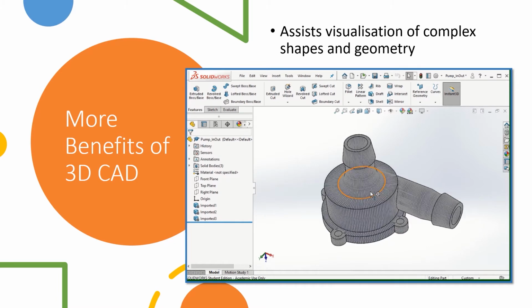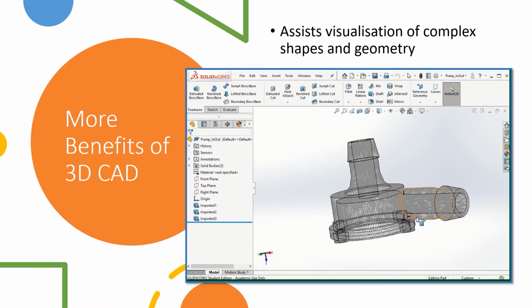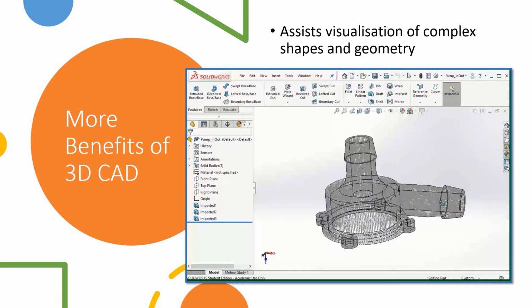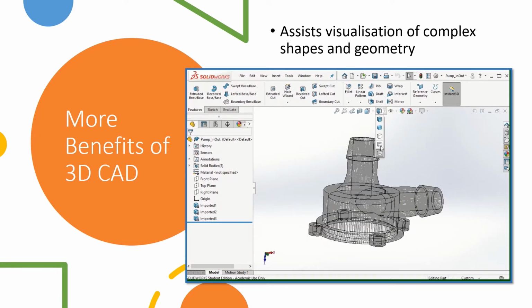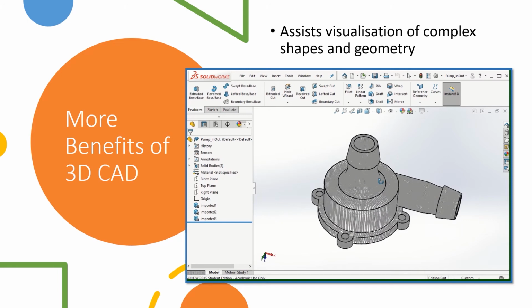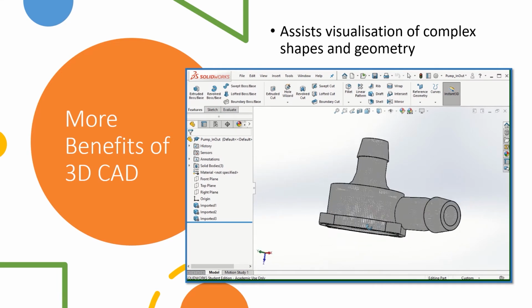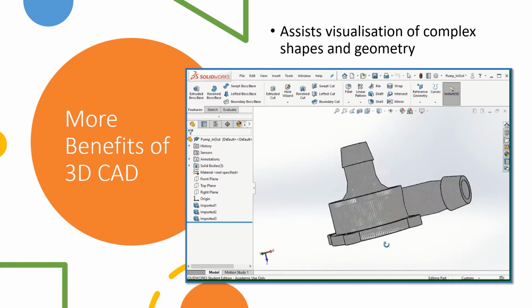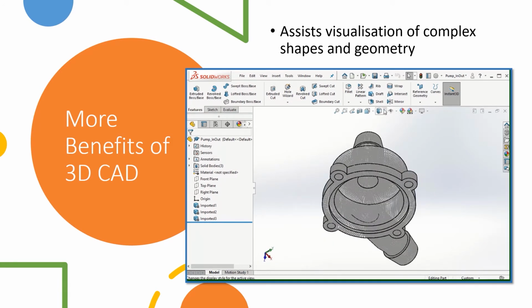So first of all, I can change how the shape is displayed. I can go into a wireframe mode, and that will enable me to see through all the different elements within this part. So I can see all the internals and externals at the same time. I can make that a slightly more simplistic line drawing, whereby now I'm only seeing the outer lines of the part, but I can still just about see through, and that can sometimes help me define exactly where I want to look with certain things.